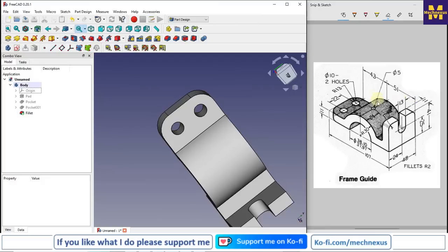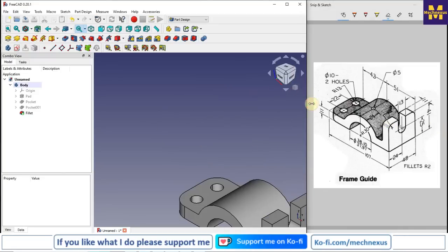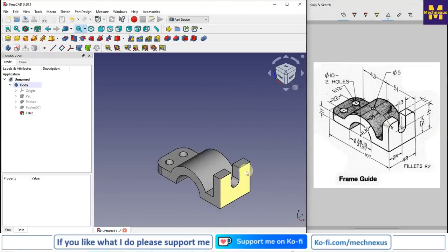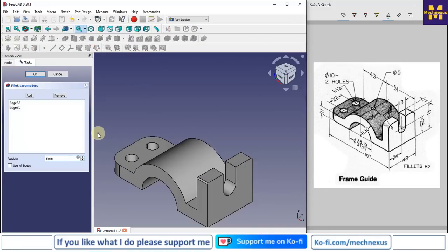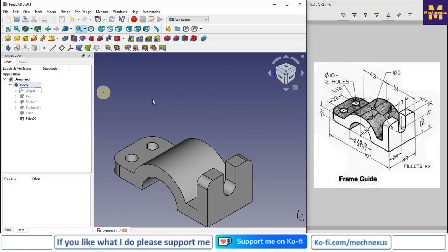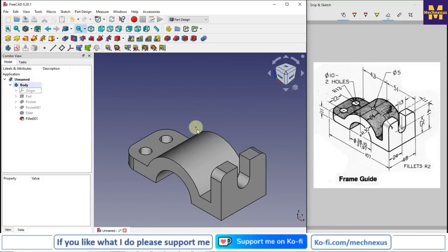And now at this portion our radius is R6. It is very hard to read, but I guess it is R6. So I will go for isometric and I will select these 2 edges and I will say 6. So the oval shape we have made here.